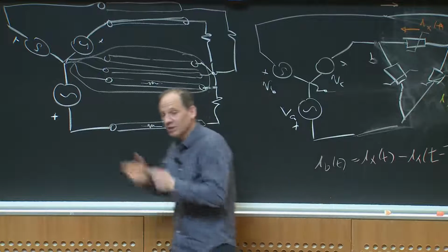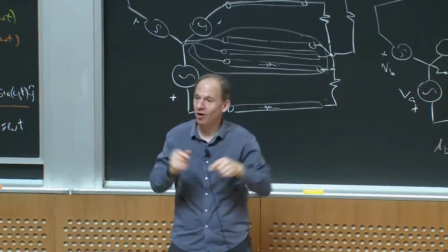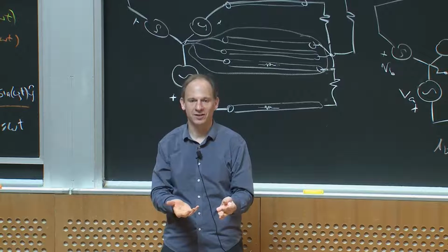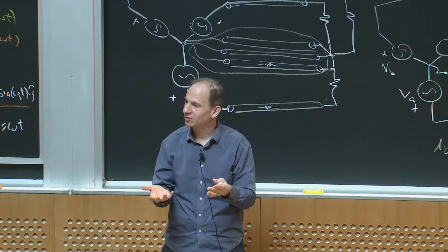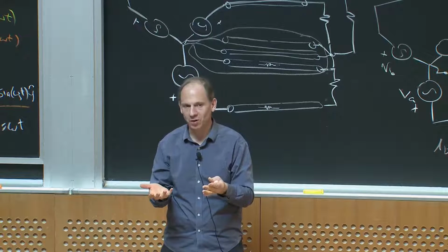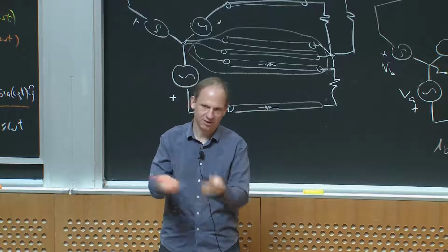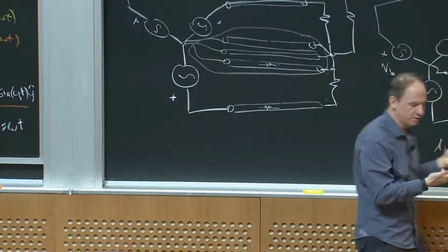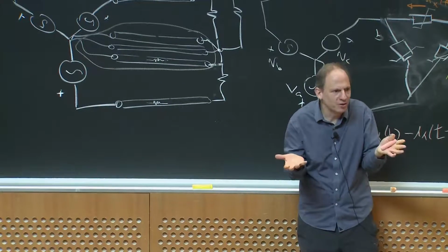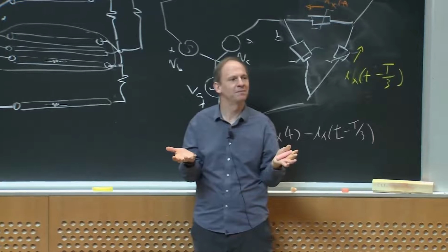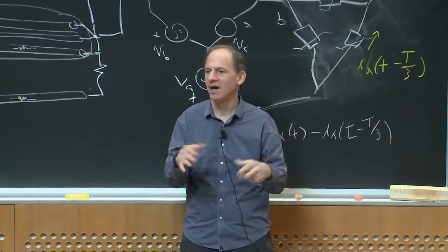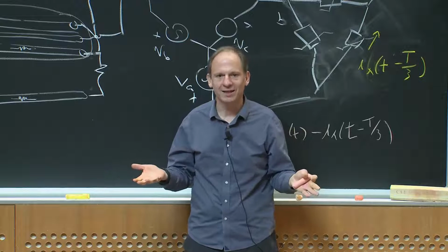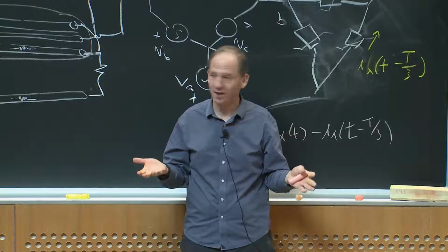Now you say, well, what if I had 4-phase? 4-phase also adds up to 0. And I can get all the benefits I talked about in 4-phase, except that I'd cancel different sets of harmonics, okay? So it wouldn't be quite as good in that regard, especially if I'm going to have things that don't have even harmonics anyways. But the beauty of it is that 3 is the simplest number that gives you the most benefit, okay? So people talk about higher numbers of polyphases, and people have worked on it. But in practice, you want the simplest thing that's really good, and 3-phase is it.